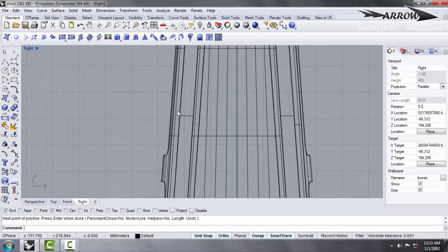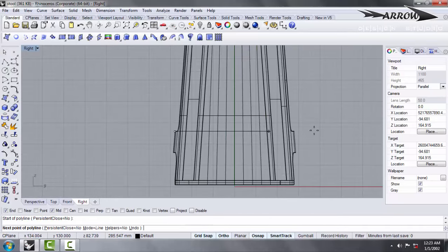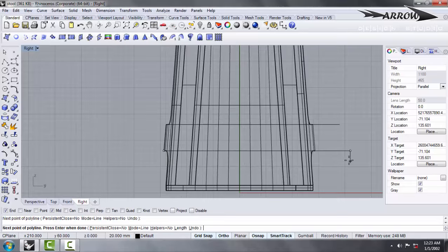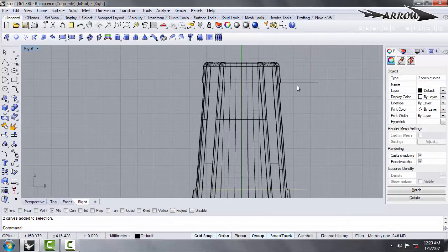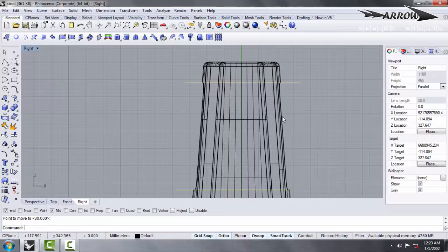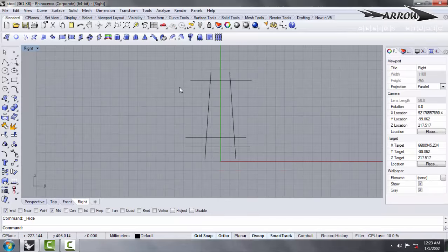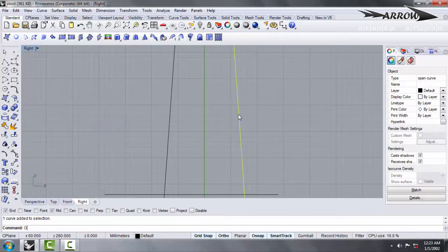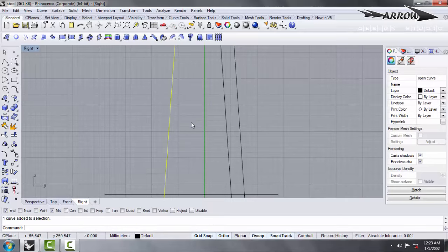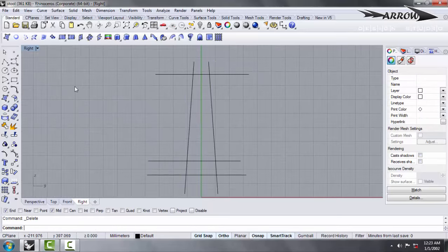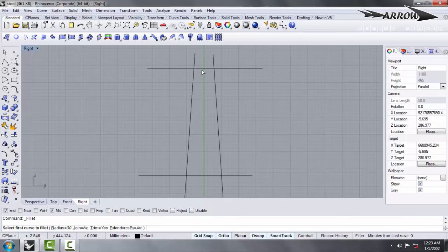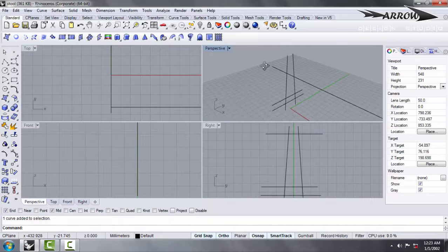Okay, the cut of this point, I say this one, the midpoint, you just need to refer because that has to be the same height, at the same height. I'll say this one and I'll say this one. So I'll just move them a bit this way so that they intersect them properly. Again I'll hide it. I've got the stuff, and again I need to say offset by 25, offset by 25. So as they were offset, now I'll say 30, fillet radius 30 over here, over here.